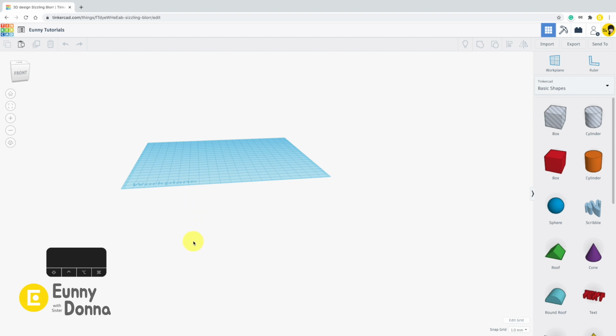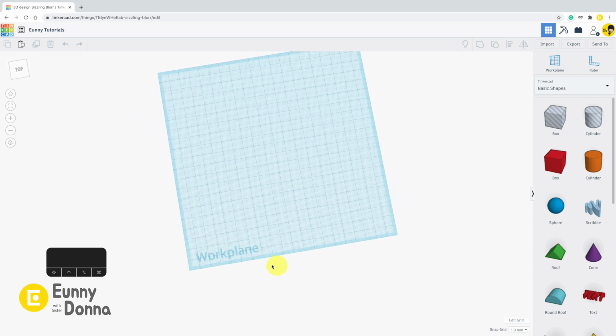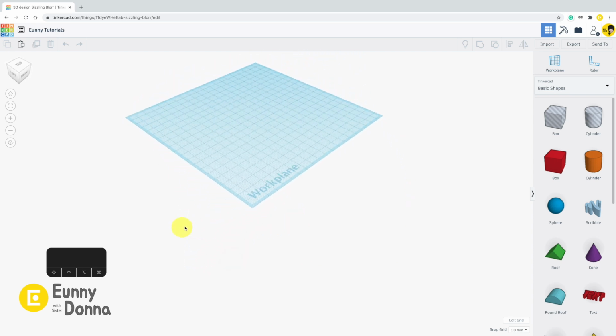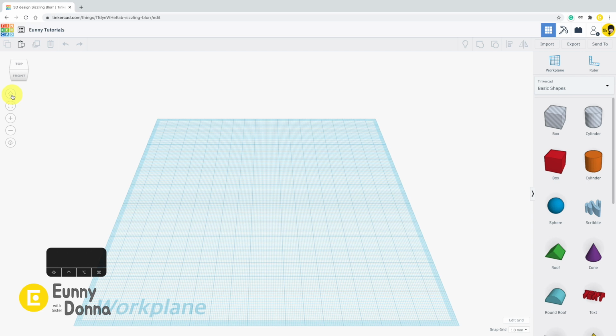If you are a beginner of 3D modeling programs, I guess this might be the most confusing thing. We are now designing a 3D object, but what we are looking at is a two-dimensional flat monitor. And sometimes you may get lost entirely. Ouch! In this trouble, click the home view icon here on your left side. Then it will go back to the right screen, facing the front top of your work plane.